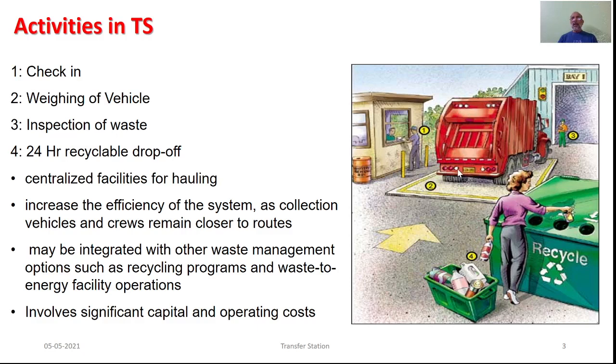As well, the further part is to know what kind of material is brought in, what kind of waste the facility is expected to deal with, and hence the waste will be studied in view of its components, its particle size, its physical characteristics, its chemical characteristics, in addition to its hazardous nature. Hence, the third step is inspection of the waste.